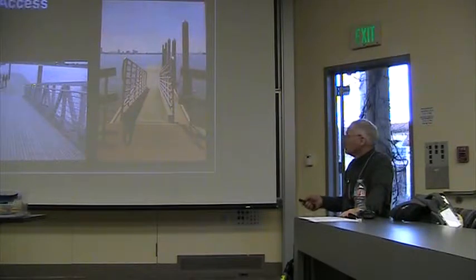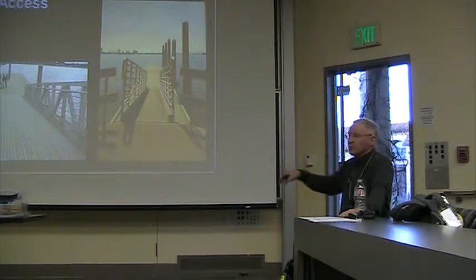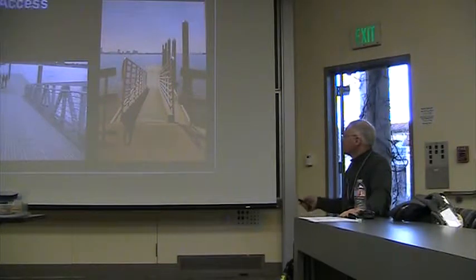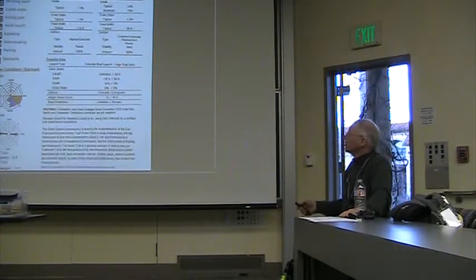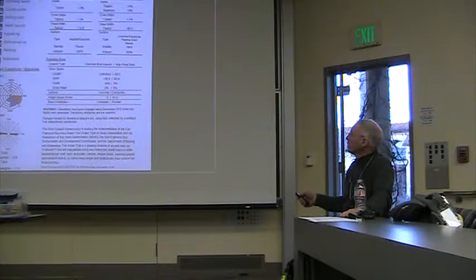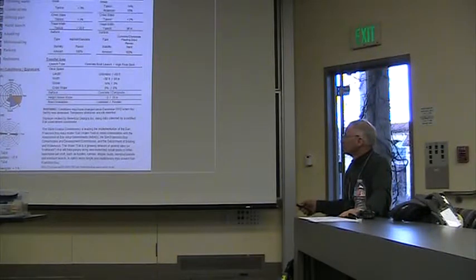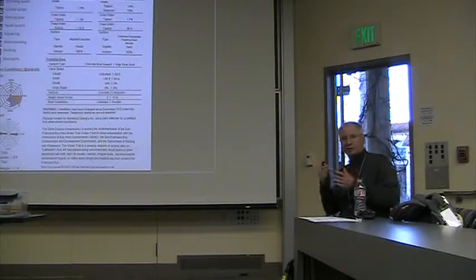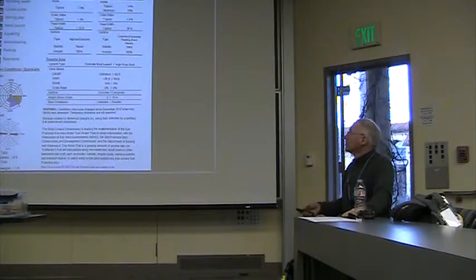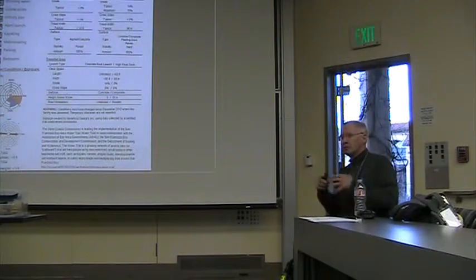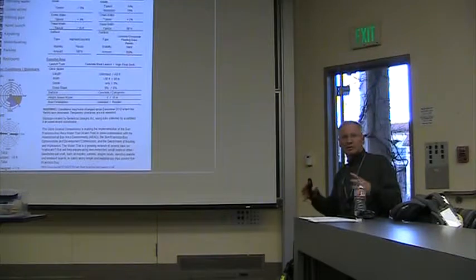Oakland. This is a really super wide ramp. It goes up and down with the tide. This is another one on another site. And then we create this access information about the ramp length, its grade, its range of grade, and its typical width. We get the water access route itself, the grades and cross slopes, and the clear spaces that are available. We show where the current is, and where the fetch is, which is the direction that the wind drives the waves. So we've come up with a way to objectively quantify all the water sites for their accessibility in the San Francisco Bay Area.